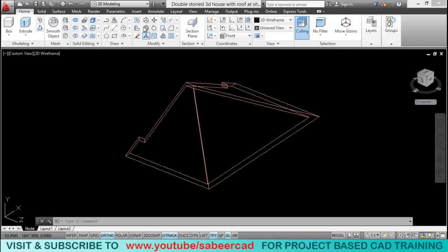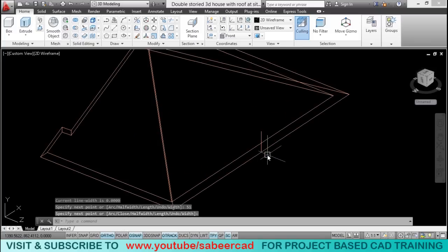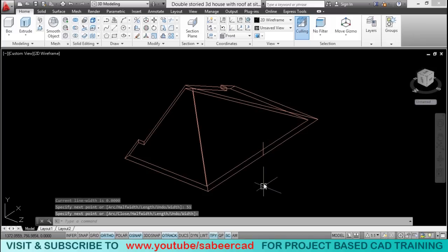And I'll click on Polyline and I'll start a polyline from this midpoint. So I'll activate OSnap and I'll click on this midpoint. And I'll keep the cursor straight up. My ortho mode is on, as you can see here. Now I'll simply type the value 51. Now I have constructed a line with a length of 51 centimeters.